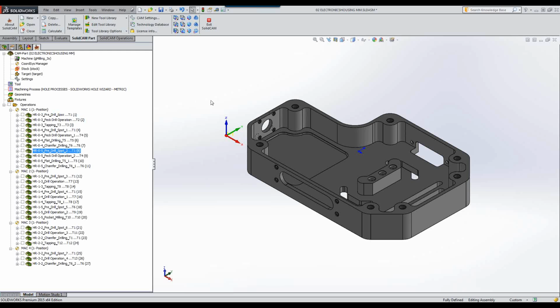If it needs a specific tool more than once, through the hole recognition and the creation of the operations, and it needs a spot drill several times, and it sees that the one that is needed has already been created, in other words, it's already inside my tool table, it will not create another one. Okay? And this goes down the line for all of these tools as well.